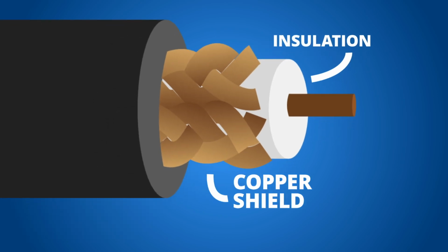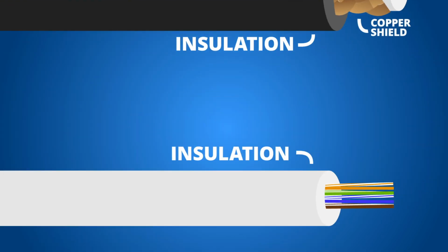And one of the drawbacks of this hack is that Ethernet cables are not nearly as shielded as RG59 coaxial cables. So if you are using Ethernet cables in your analog CCTV setup, you just have to be extra cautious about where you are laying that Ethernet cable. Make sure it is well out of reach of any cables that could be sending high voltage electric signals to interfere with your video data. So those are the two main mistakes that we see most often when it comes to video interference. One, your cables are not high enough quality, or two, your cables are not properly installed.